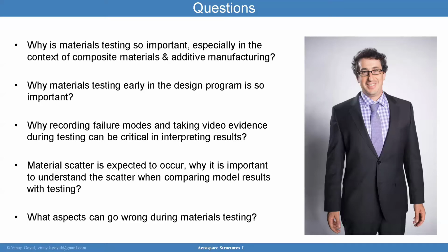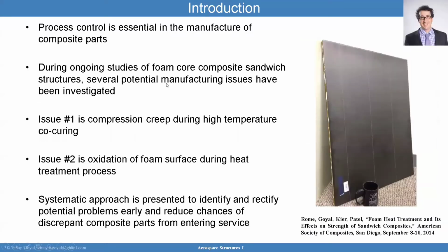Yeah, once you flip to the first one. The most basic part here is, if you're a designer, an analyst, or anybody involved in designing or manufacturing an aerospace part, of course you start out by choosing your materials, and you choose them based on their strength, their stiffness, their high temperature and low temperature properties, maybe their fracture resistance, maybe their impact resistance, maybe just whether they've already been characterized.